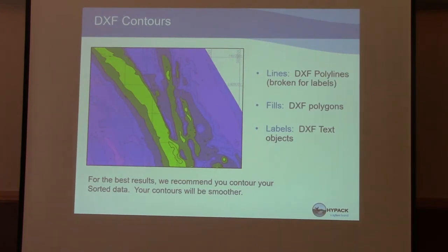With the DXF contours, you can fill the contour, you can have just straight lines, you can change the weight of the lines, you can change the intensity, make every 10th line stronger. There's a lot of things you can do with contours to make them stand out.